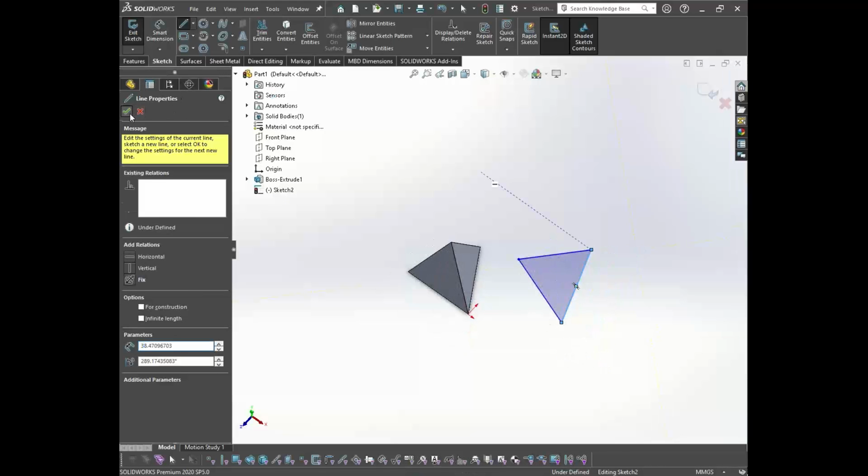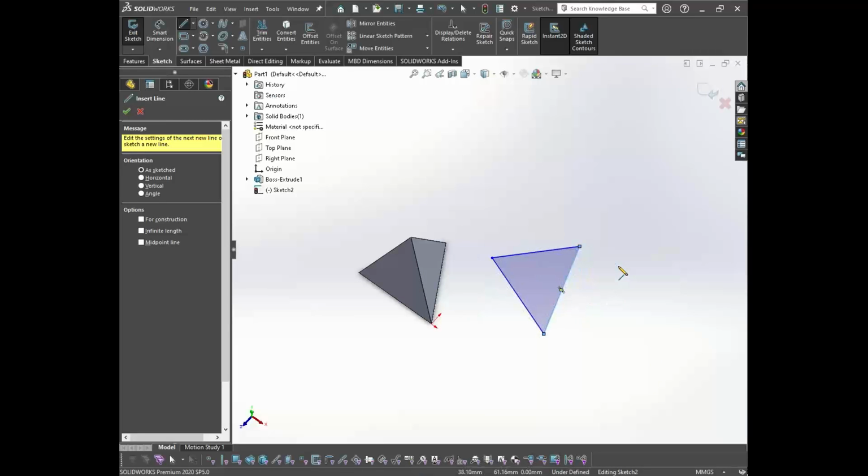If this is my single element, whenever I am dealing with sheet metal components, which have certain length, certain breadth, but the thickness of the sheet metal component along the cross section is constant, at that time I can use the shell elements. When we see this analysis performed in detail, you'll understand it in a much better way. I'm just telling you what the shape of these elements is.